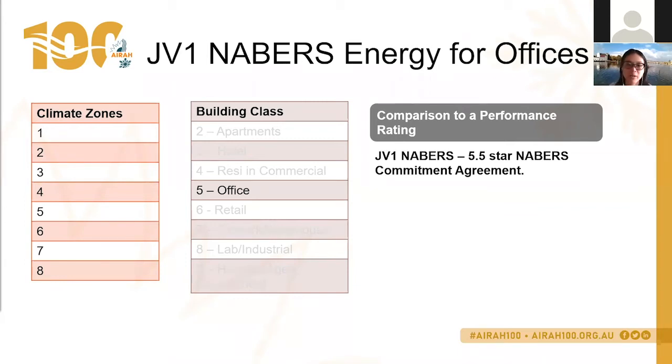Whatever design you're putting in, you need to run the PMV calculations and ensure that PMV plus and minus 1 is achieved in more than 95% of occupied floor area, more than 98% of the time, with time defined as the annual hours of operation. This PMV requirement, or thermal comfort requirement, is consistent across JV1, 2, and 3, where you're expected to undertake energy and thermal modeling.